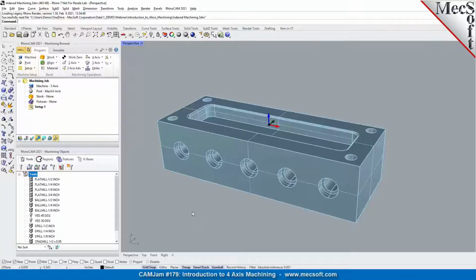We also have a true four-axis method, which we'll be covering in one of the other webinars, where you can have all three linear axes and the rotational axis, which makes it a full or true four-axis machining. The four-axis methods that we're going to be talking about here will involve using a rotary table where the part is being rotated on a rotational axis on your machine, or which can be held with a rotary chuck and a tailstock, or however it's being held on the machine. So the part is able to rotate and the tool will remain normal or perpendicular to your axis of rotation.